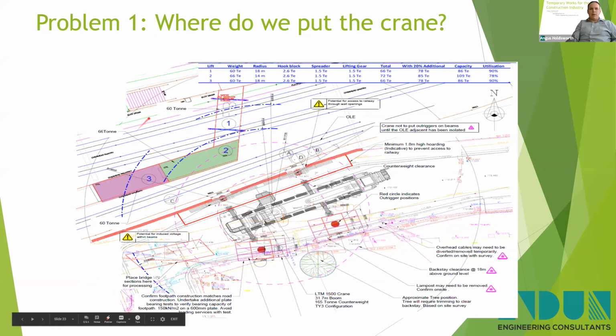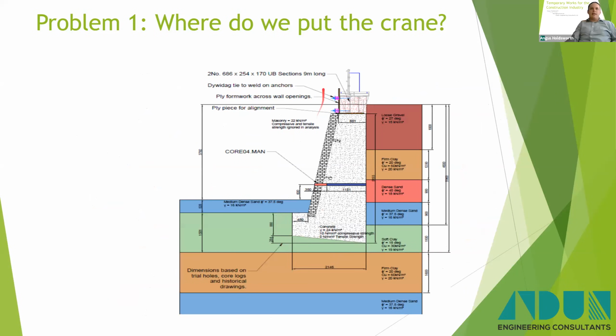You can see here the back of the footpath, so the road front of the building is just there, which meant that the other outrigger was going to be sitting behind the wall or very close to the wall. Putting a large outrigger load behind a masonry retaining wall is never a great idea if you can avoid it. So we came up with a solution where we placed the outrigger directly over the top of the wall, which thereby makes it a stabilising load.